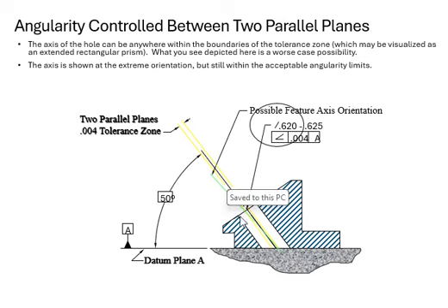So again, the axis can be anywhere in that range, which is the tolerance zone. And that range again is 0.004. So that means the 50 degrees plus or minus that. Of course, that zone is acceptable for manufacturing processes.